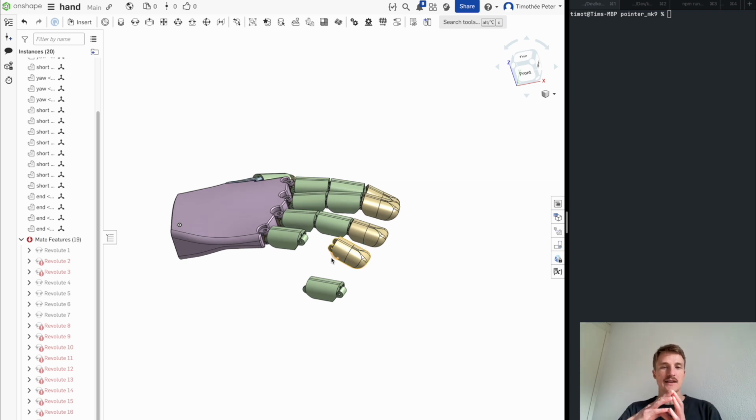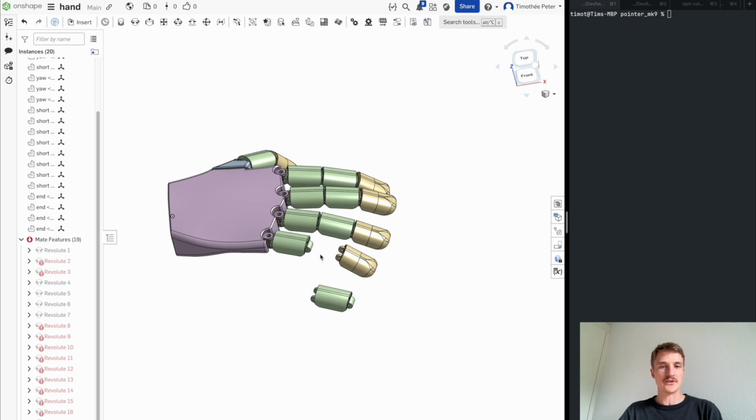And so really the issue that's happening here is that the way we do CAD today is we start with sketches. Those sketches define the geometry. So the geometry depends on the sketches. And then the assembly depends on the geometry. Because there's this dependency always on the previous step, it means that if one of those steps is broken, all the rest of the assembly process is going to be broken as well. And if we start thinking of how to automate the assembly process and the version control process of very complex assemblies, we can see that this process just doesn't work. It's not stable enough to produce repeatable results.